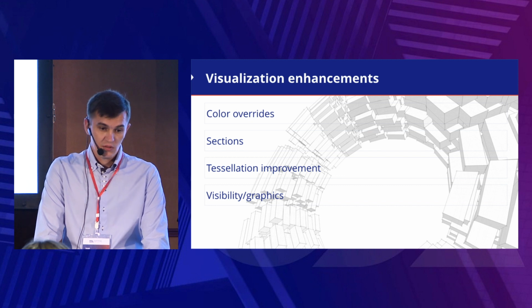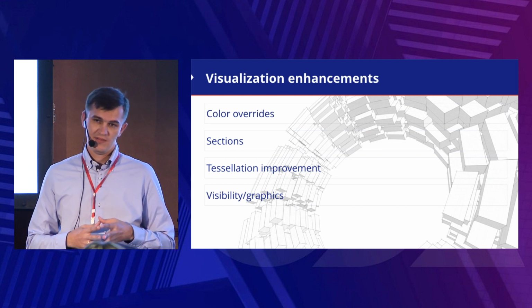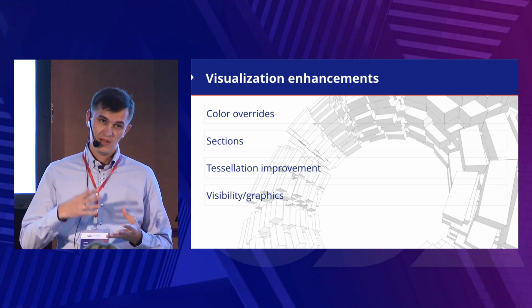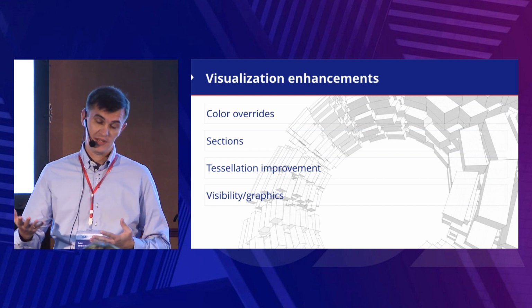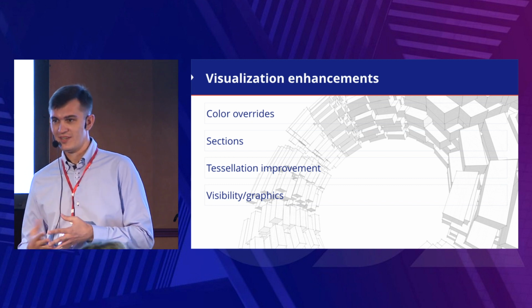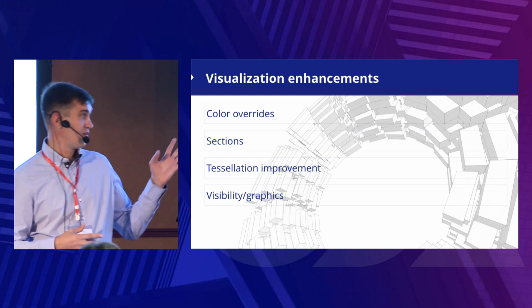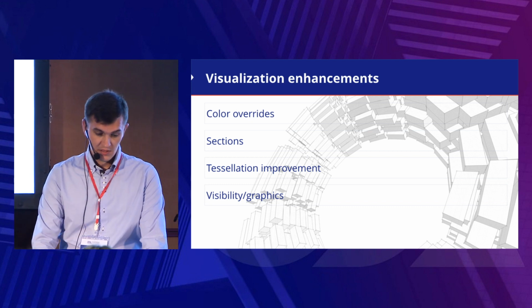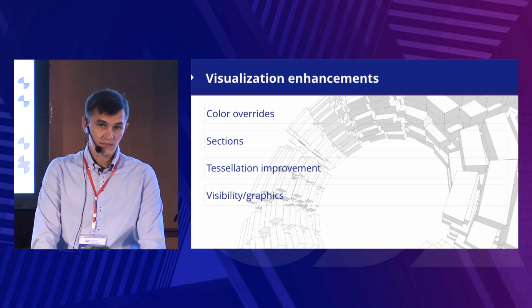And also in this file we'll apply override by category the walls, and this override by fill pattern and by color, and you can see result on all other walls. So next enhancement is sections.